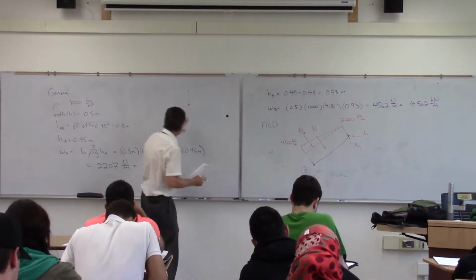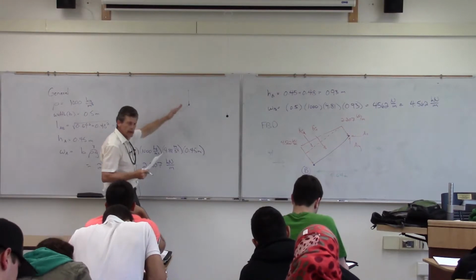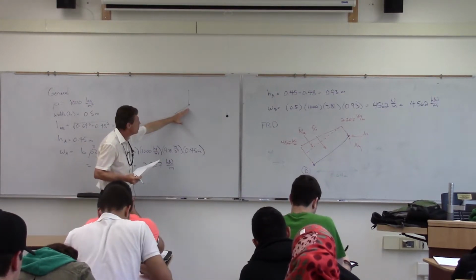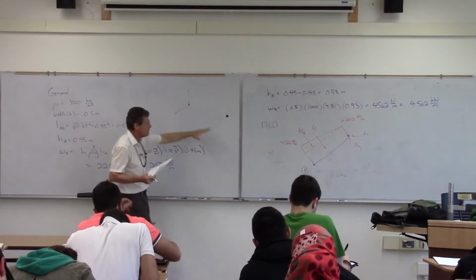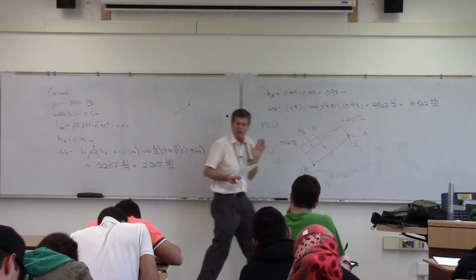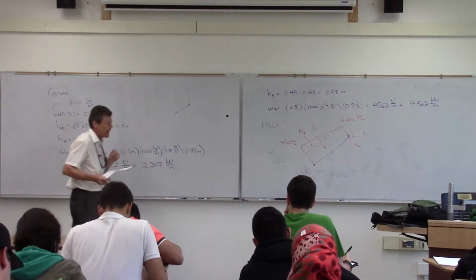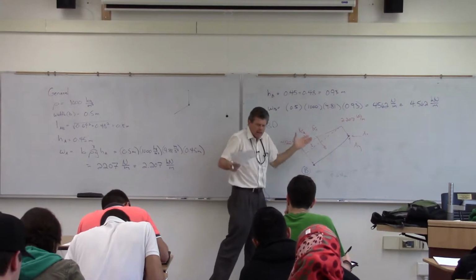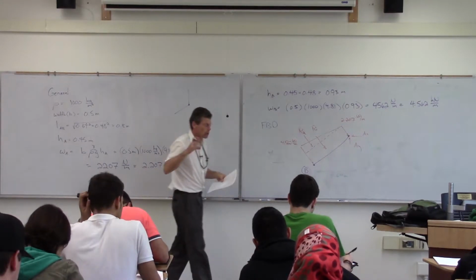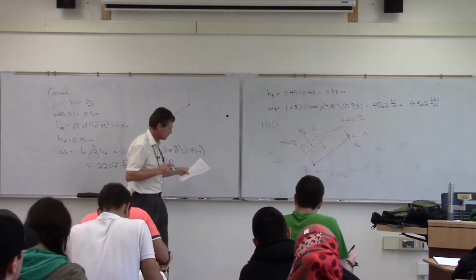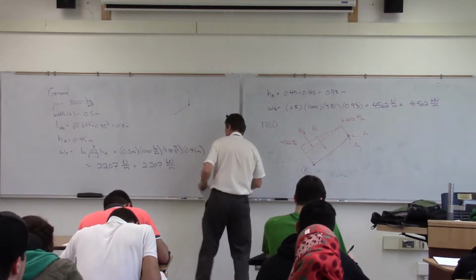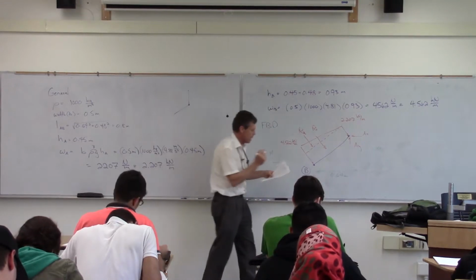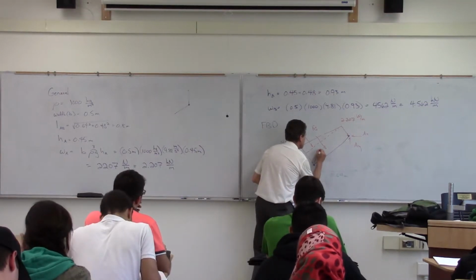Okay, so what we've done is we've modeled that, and again, taking the fact that we know that the load is going to be acting perpendicular to whatever angle that particular plate is at. So it's acting perpendicular, it's going to be acting at this angle. Now the nice thing about perpendicular is when we get into moment equations, it'll make it a whole lot easier. We're not completely finished with our free body diagram, because the one other piece we want is this cable FBC.